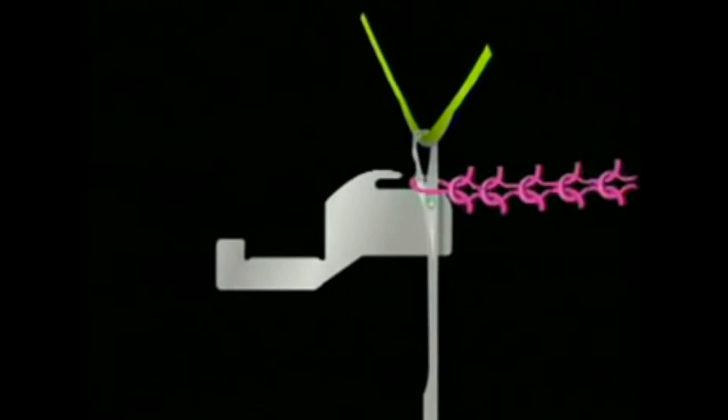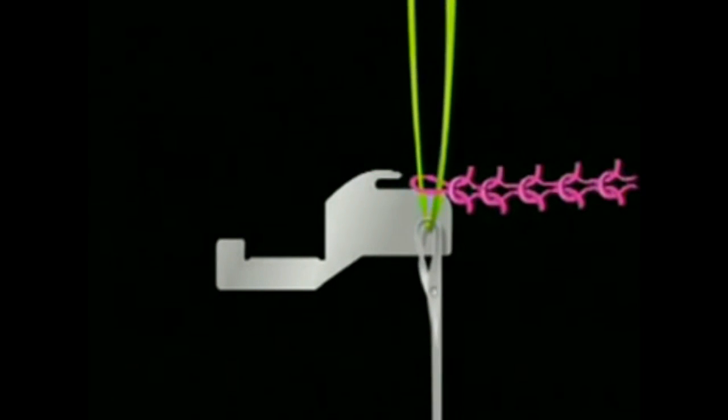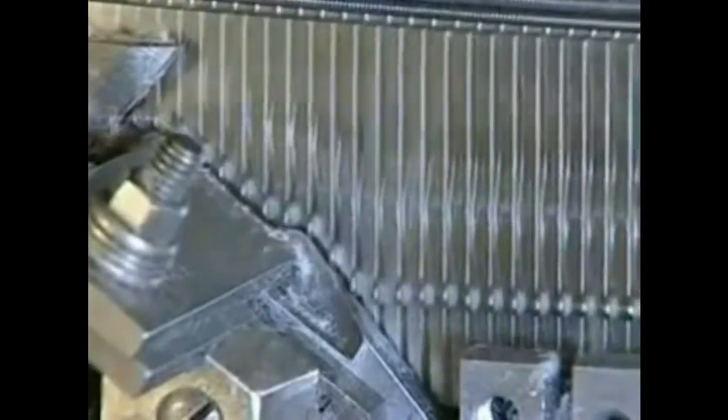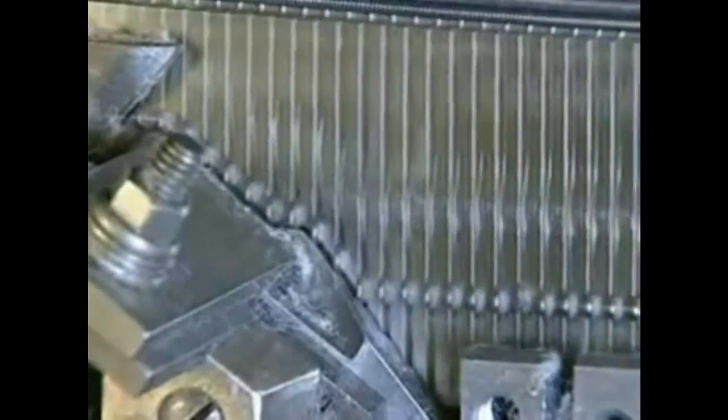Since the fabric can't go up with the rising needle, the old loop now clears the latch. When the hook catches a feeder yarn as the needle moves down, the sinker moves back out of the way, and knockover, cast-off, and stitch forming takes place. As the new stitch is formed, the fabric rests on the top of the nose. Here's one last view of needle activation to show you how knit fabric is formed.